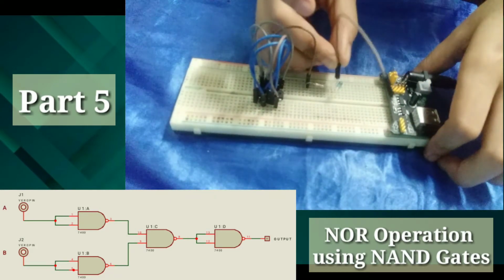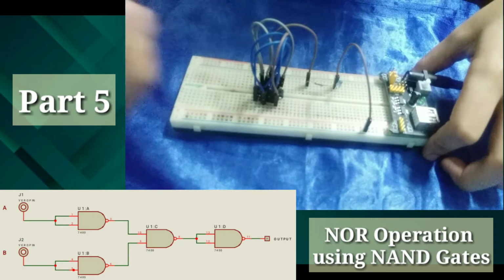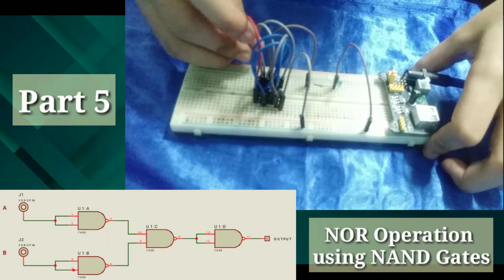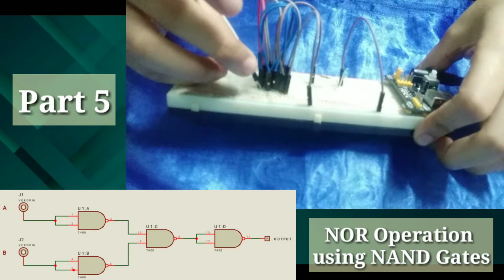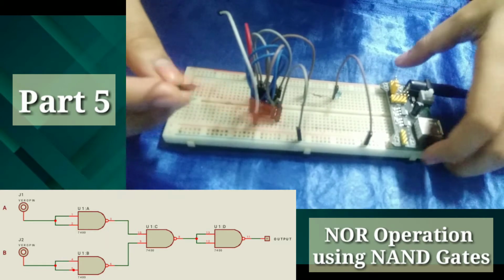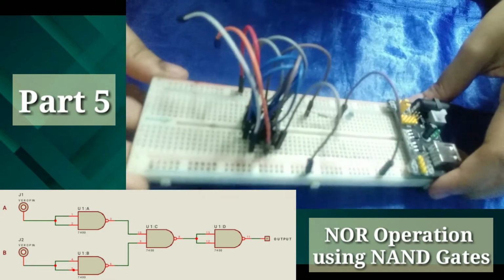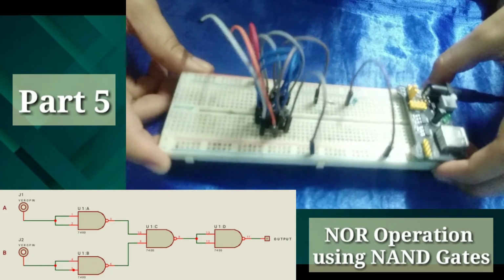Now, let's ground all of our components. So here in the ground. Then don't forget to ground our integrated circuit so that the LED will light up. Then of course, don't forget our VCC, which is connected to our voltage supply. Don't forget our inputs. So A is connected to pins number 1 and 2. Okay, so white is for A. And our orange wire for B is connected to pins number 4 and 5 of our IC. So, there it is. This is how our circuit will look for part 5.